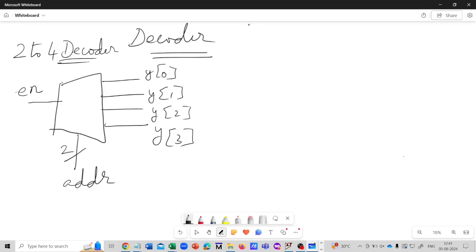But unwanted transitions in the logic and in the nets will lead to unwanted power dissipation, because for CMOS we know that switching activity will lead to dynamic power dissipation, which means if the transitions in the address line propagate to the input, then there will be unwanted dynamic power dissipation, which will drain the battery life.